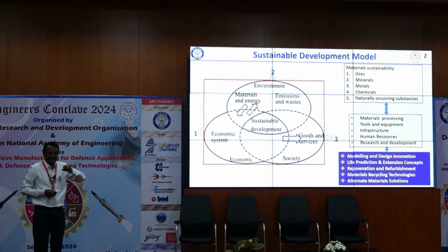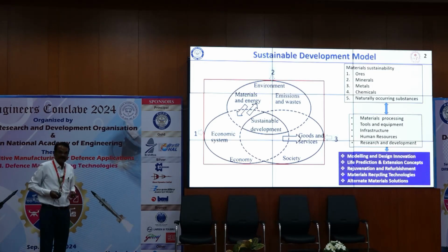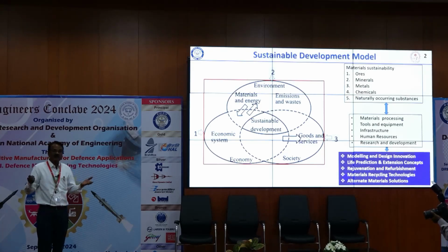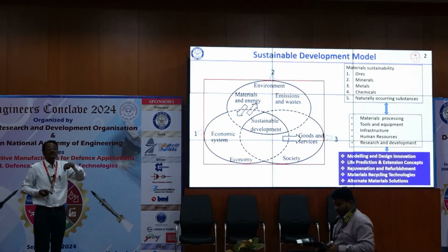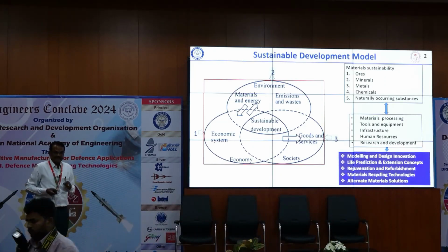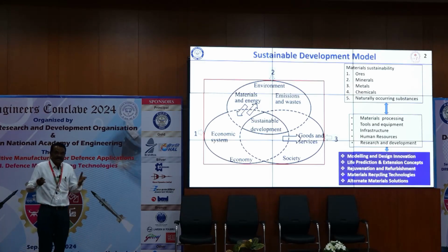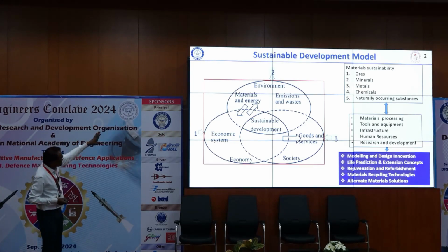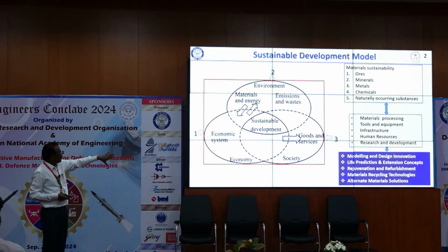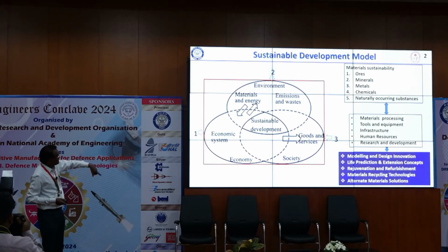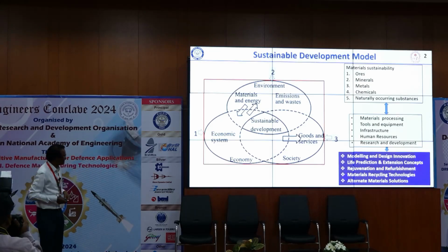You take America, France, Russia, and China. You take France, SNECMA, they developed an American alloy. They have removed niobium, hafnium, reduced it substantially. They have considered molybdenum because they have plenty of molybdenum. Likewise, United States, Inconel 718, they have introduced cobalt because they have availability. And China, FGH 95, high strength nickel-based superalloy. They are not dependent on any alloying elements, they are dependent on grain size refinement and achieve the fatigue resistance combined. So these are the considerations when we develop the materials or use the material, develop the processes. We have to have a linkage, what is available, what is not available to meet the ultimate requirements.